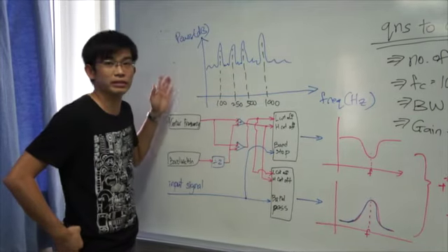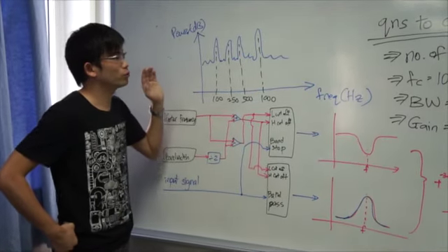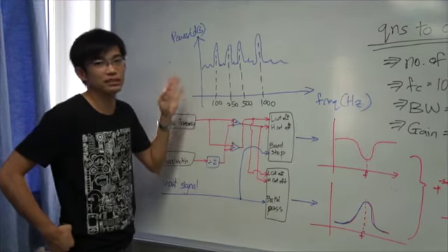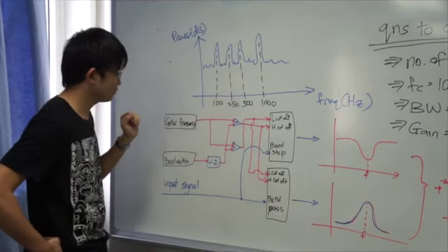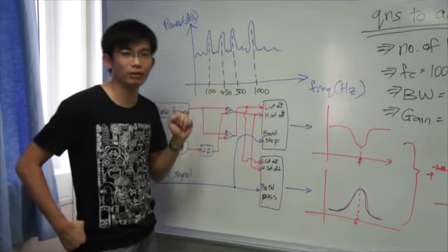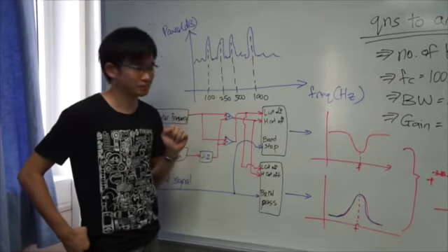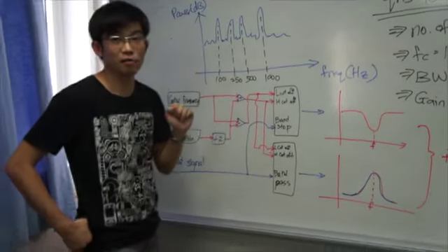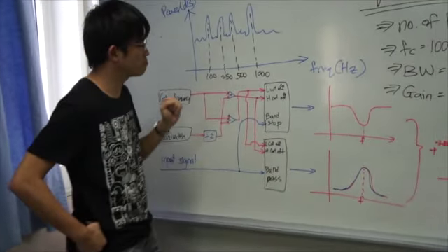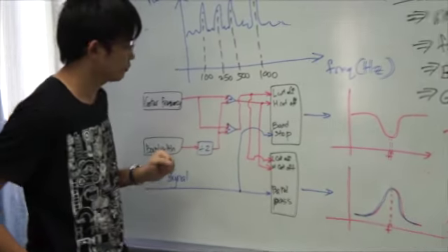Okay, as previously mentioned, we identified 4 tonal noises in the musical signals. Therefore, we have to design a 4-band equalizer to clean out the noise. The design of our filtering system consists of bandpass filters and bandstop filters.